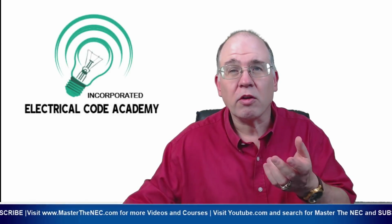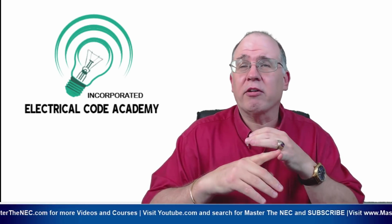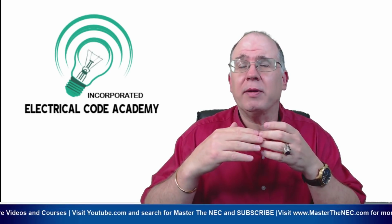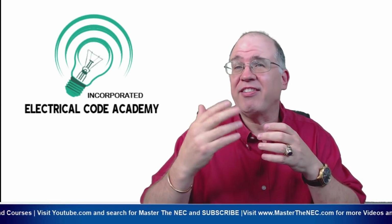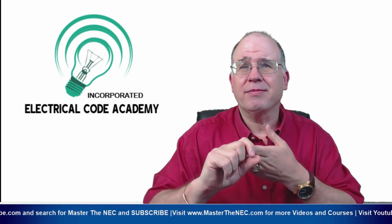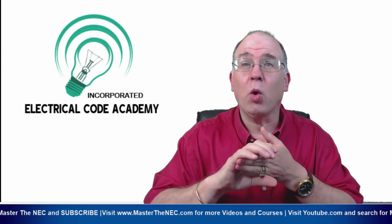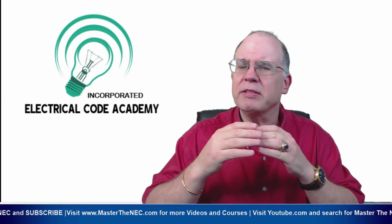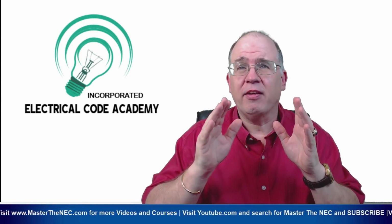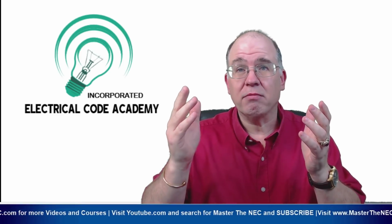Okay. So, it can get confusing when you read all these codes. We know that in a regular raceway, when we had 4 to 6 conductors, we had 80% adjustment, and with 7 to 9, we have 70%. We have all those. What this is saying is, okay, if you meet A, B, and C, and you have over 20 current carrying conductors based on bundling for 24 inches and more, but you met all the other rules, we'll let you do it, but you're going to apply a flat 0.60 or 60% adjustment factor. No more than that, no less than that.